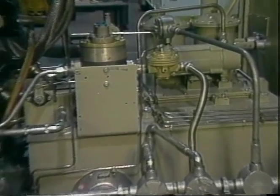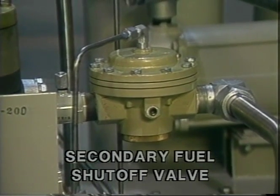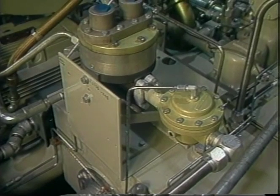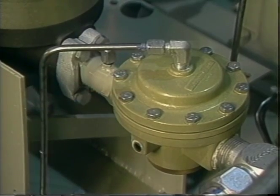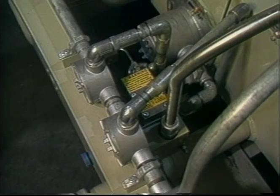The secondary fuel valve is a 2-way, spring-loaded, diaphragm-operated, normally open valve. It is located on the fuel manifold downstream from the primary fuel valve. The secondary valve acts as a backup to the primary valve in case the primary valve fails to close due to contaminants or other factors.